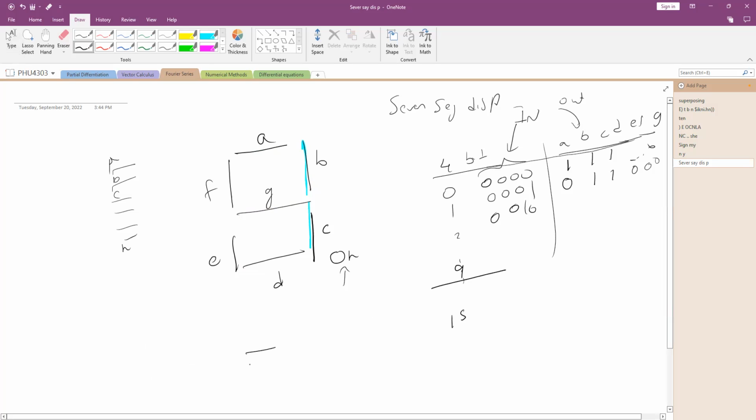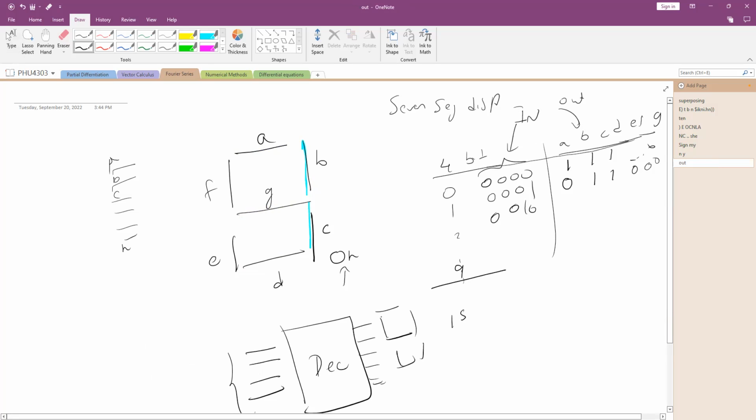So you have 4 inputs coming here like this. You have your decoder circuit, and 7 outputs going like this, which connects to the 7-segment display. So when you represent a number using binary, 0, 0, 1, 0, something like that, the respective value should be displayed here using the SSD display, the 7-segment display. Is it clear?